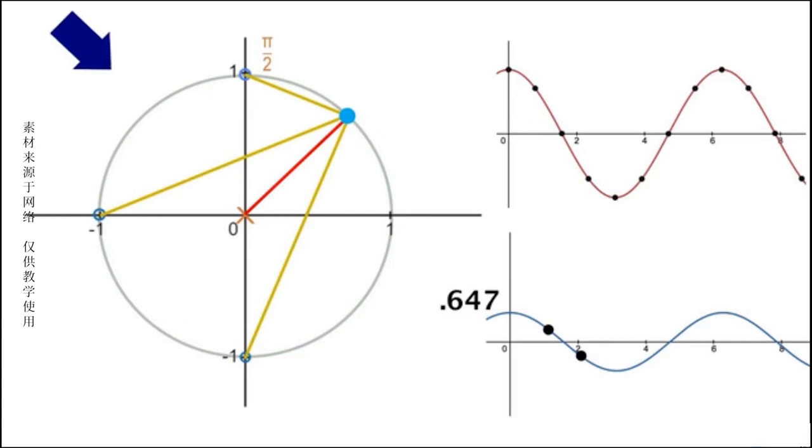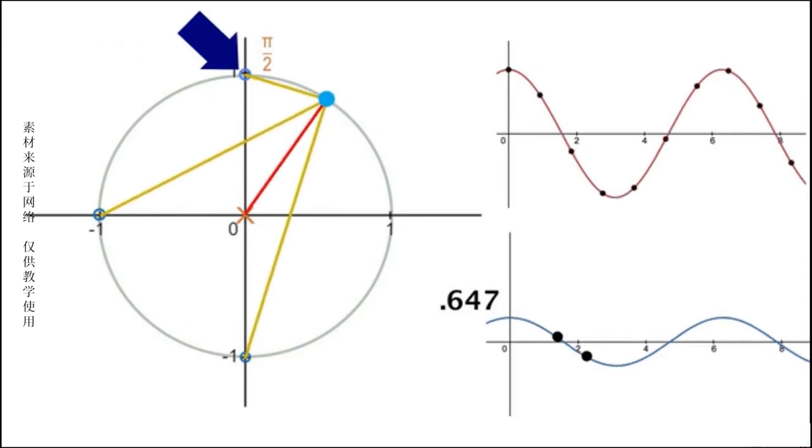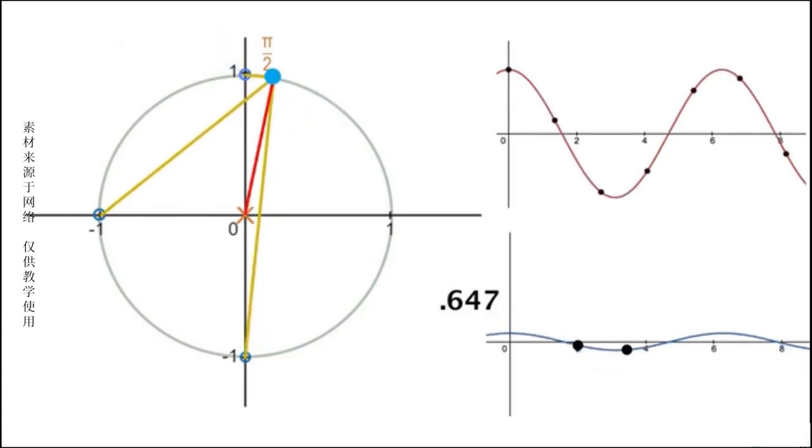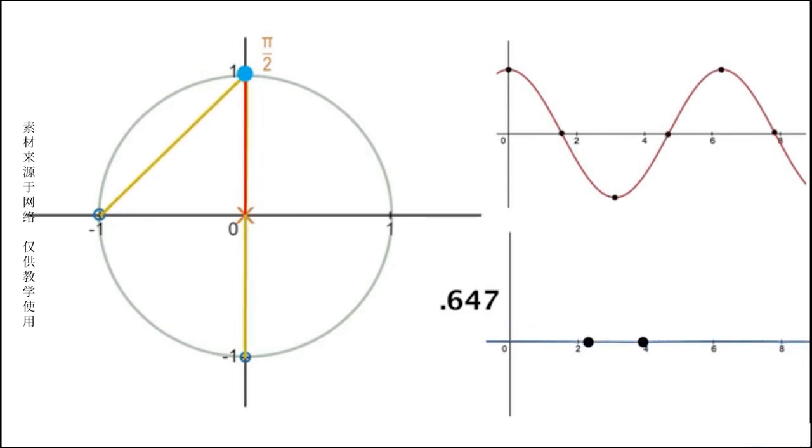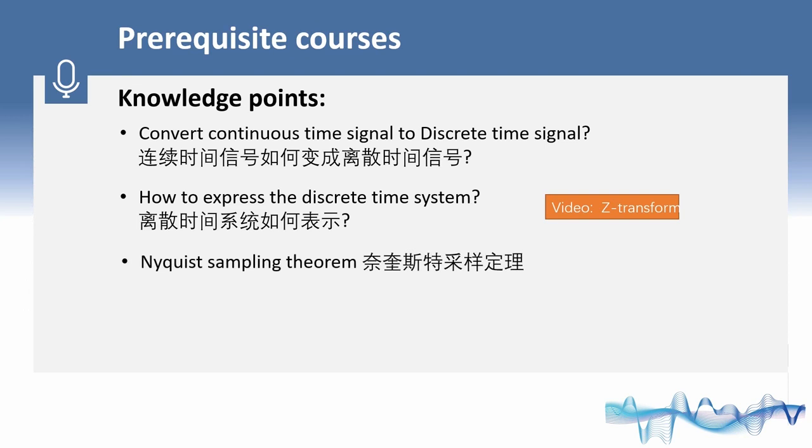This 0 here at pi over 2 means as we slide towards that, the output amplitude also goes to 0, which we can see here since the average of any 4 neighboring samples now is 0. Now I've been using one sinusoid this entire time of one specific frequency, but that's really all we need in order to analyze any signal. The next question is, do you know Nyquist sampling theory?